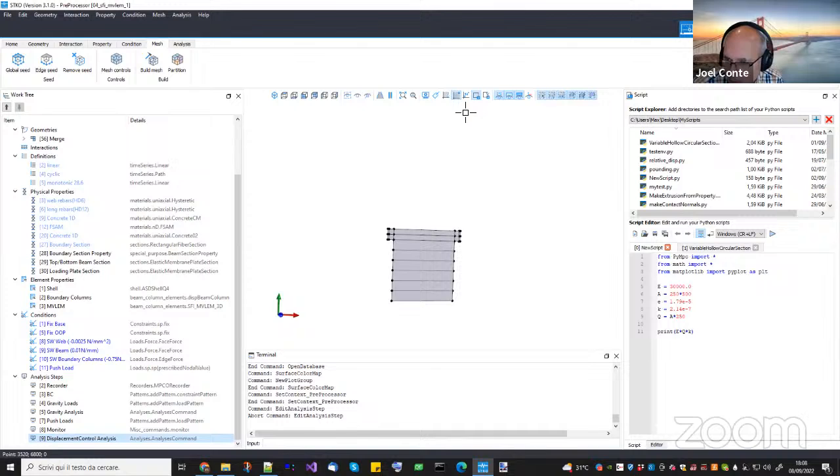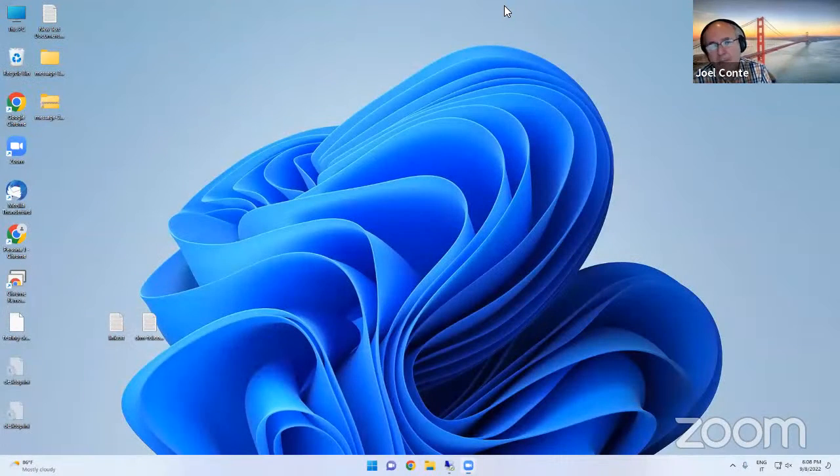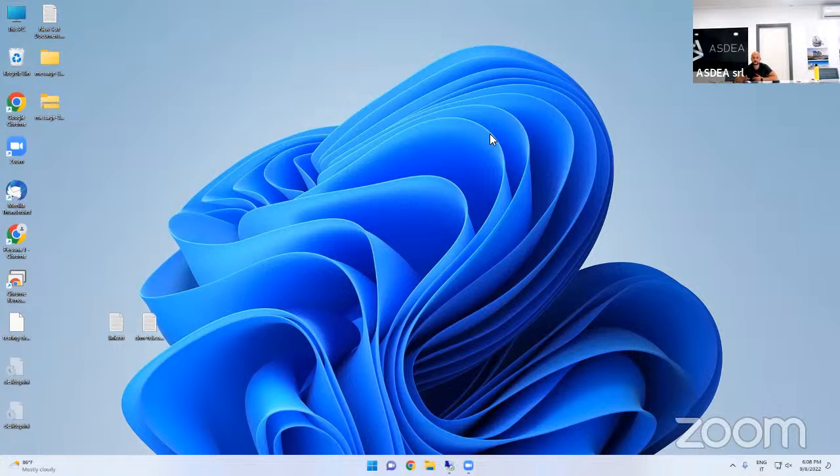And then Massimo, one question here about Lin's question is, it could also be related to what we were discussing, right? The bifurcation problem where you could have many equilibrium branches, and then if you use a large load step, you skip over this complexity, by chance, I would say in some cases. And sometimes you pick a wrong path that you may not want. This is one of the main problems that you have with softening.